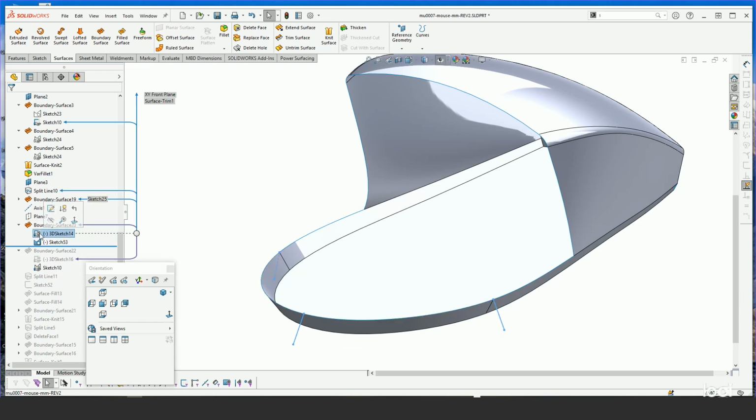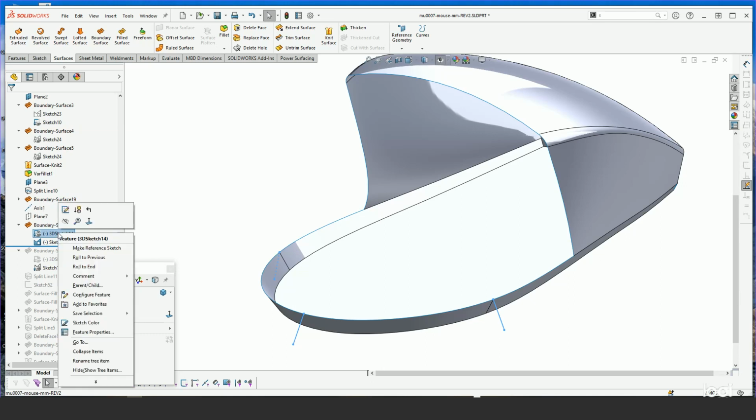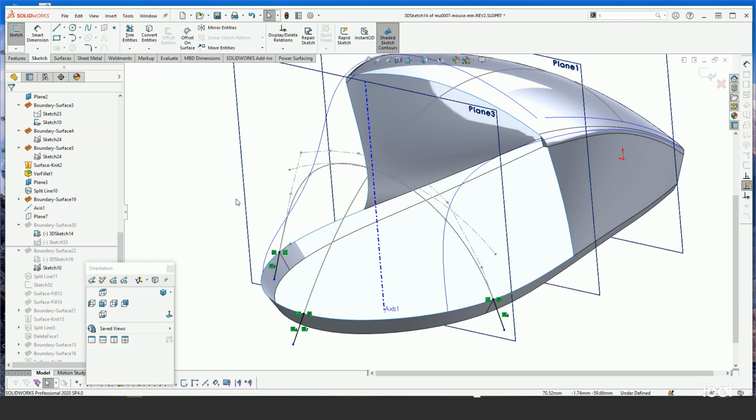So when I do reference surfaces, they're always the same. I do them exactly the same way almost all the time. And basically they are created with two sketch entities. The first is a 3D sketch that is basically a few lines that are constrained to some existing curve geometry.